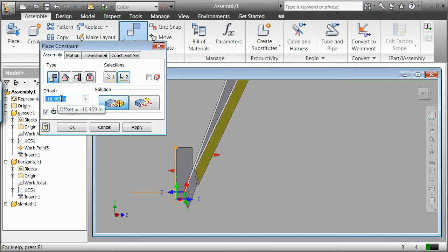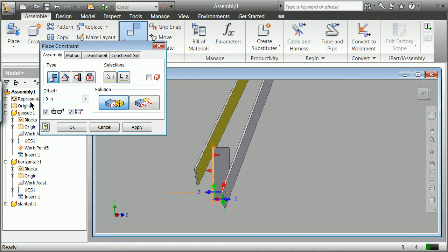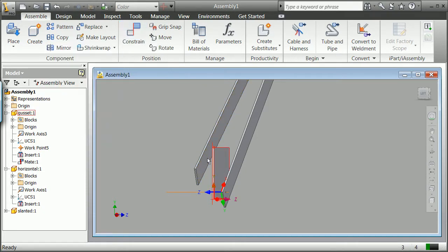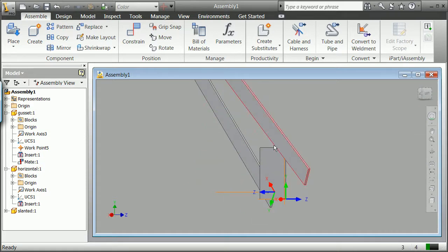and realize it sets this offset here. It's pretty interesting that it sets that offset. It more or less makes them parallel, but you can then set that to 0, and you realize that that goes ahead and constrains it to probably the way you want. And now as you move it around, kind of pulling it and maybe make it down towards a hole or something, it stays constrained along there. This is moving in that flat plane.